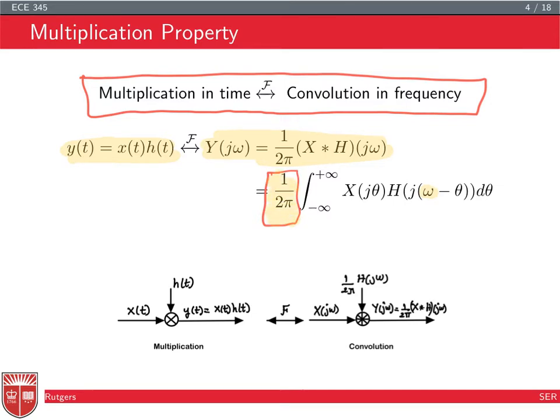Now you may think, why do I care about multiplication in the time domain? Well, we just saw an example in the previous lecture where you want to do modulation by the carrier frequency to shift the frequency of your signal, whether it's audio or video, to a frequency that you can transmit that is maybe dictated by the standards, such as your TV if you're receiving cable, or you're receiving wireless video, wireless 3G or 4G or any wireless system.